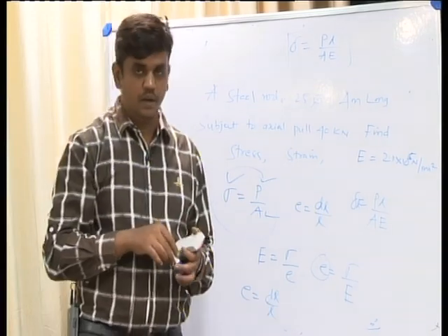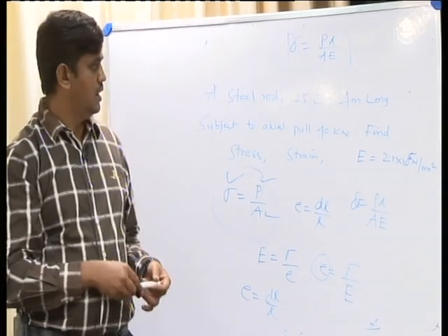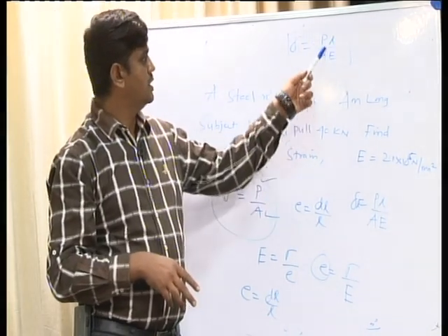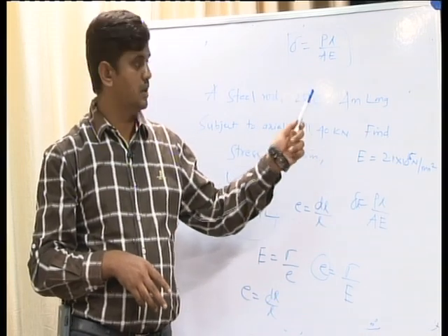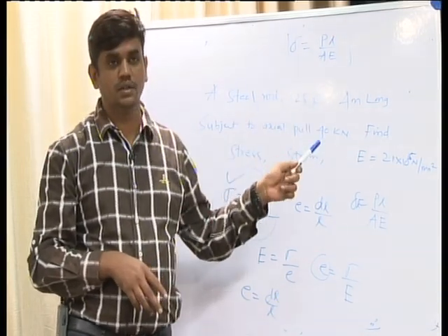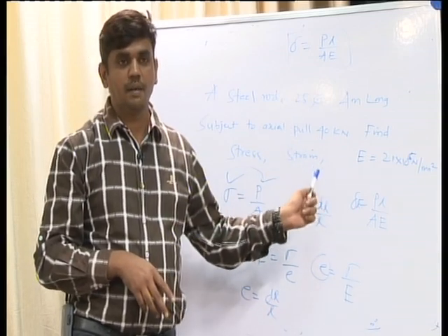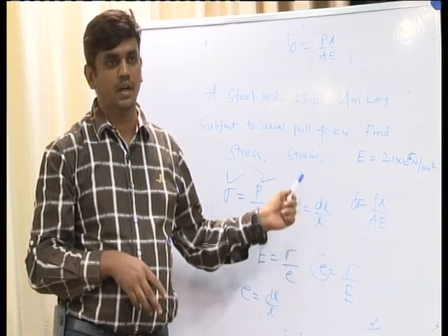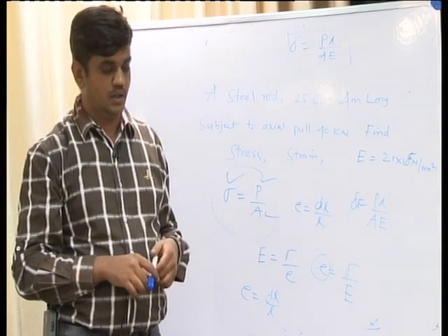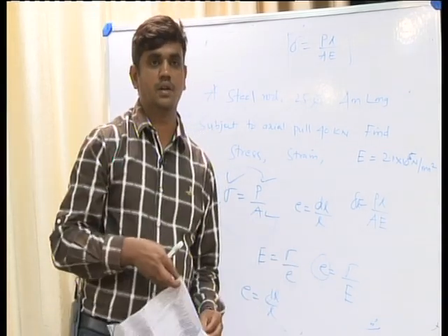So remember, to calculate the unknown values P or area or the Young's modulus, use this relation, and care should be taken to convert the units, that is kilonewton to Newton, meter to mm, gigapascal to Newton per mm square, megapascal to Newton per mm square, and remember the relations. So next class we try to learn about composite bars and elongation of bars. Thank you.